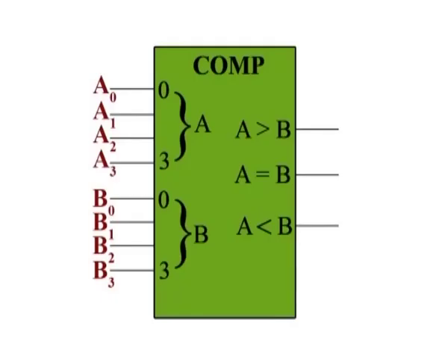Inequality. As shown in the logic symbol, for a 4-bit comparator, in addition to the equality output, many IC comparators provide additional outputs that indicate which of the two binary numbers being compared is the larger. That is, there is an output that indicates when number A is greater than number B and an output that indicates when number A is less than number B.